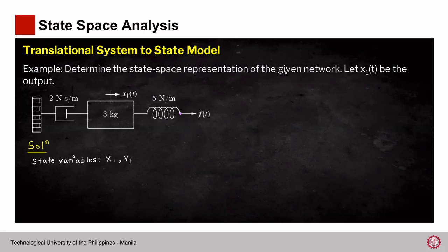If you still remember, the solution method that we had here in our class, to understand how it works, we actually put here a zero mass. Naglagay tayo ng zero mass diyan, because I've told you in class that you can only apply force if there's a mass. However, that zero mass is actually zero in value. So therefore, hindi mo siya assignin ng state variable. So kung may another block diyan, as in solid block talaga na may mass, then that's the time that you put x2 and v2 as another state variables. But as it stands, ito lang muna yung ating state variable. So we have x1 and v1.